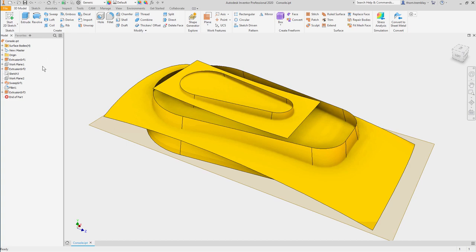First, we have Extrusion 2, which rises above Extrusion 3. I want to use Extrusion 3 to trim Extrusion 2 to give it a more complex top edge. So, in the surface panel, which was turned on using the pull down on the 3D Model tab, I'll select the Trim tool.